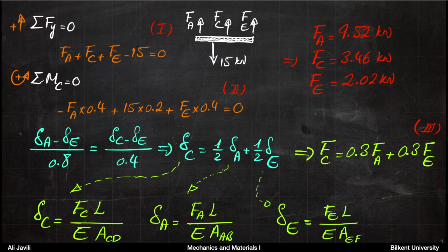So it's sort of important that if you look at FA, FC, FE here, these are the forces acting on the rigid member. But when you use them inside the equations that we had for axially loaded members, these are now considered such as internal loads. Okay, so this duality between being external, internal, you should always pay attention to.